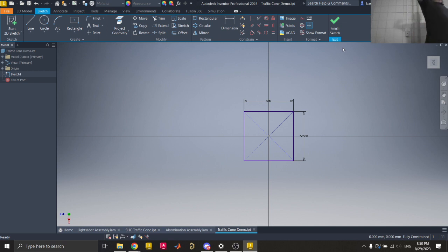One thing I'll mention, everybody, there is more than one way to make a square. If you want to just make 4 lines, you can do that. If you want to use this little rectangle tool, you can do that too. Any way that you want to make 4 lines, as long as they are dimensioned properly, perpendicular to each other all the way around and centered, you're just fine. So there's plenty of ways to do that. There's the first option we did earlier with adding measurements around for everything, or this rectangle tool. Is everybody good if I move forward past this rectangle?